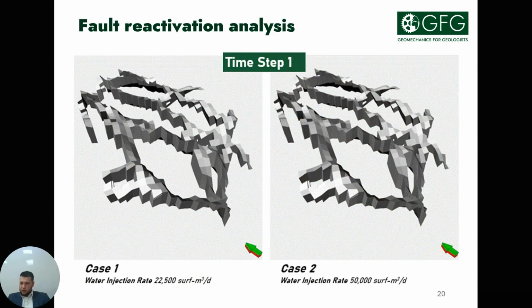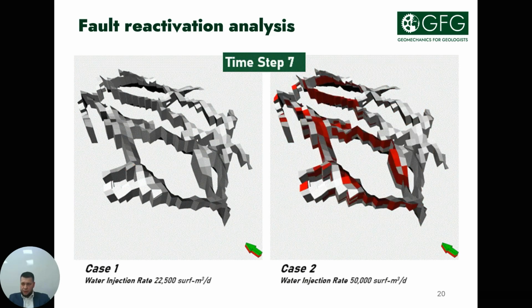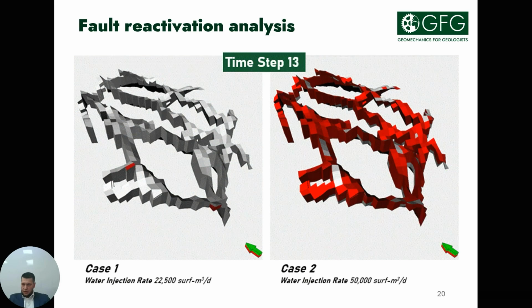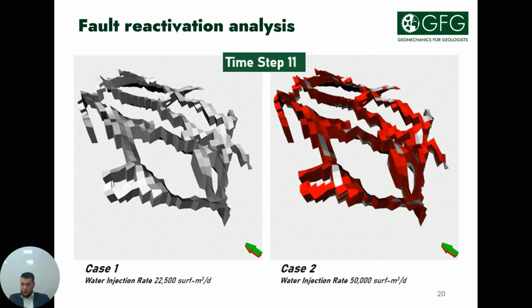Discrete fractures and faults are also typical for zones with high tectonic activity. The reactivation of faults and their displacement is especially dangerous. Absence of taking into account the properties of faults can lead to losses during drilling, damage of the wellbore casing, activation of reverse fault and normal fault, and other effects.